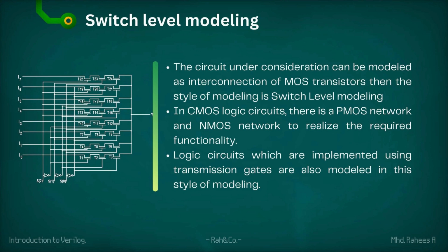Here in the diagram, an 8:1 multiplexer is represented as an interconnection of various NMOS transistors. The circuit under consideration can be modeled as interconnection of MOS transistors. Then the style of modeling is switch level modeling. In CMOS logic circuits, there is PMOS network and NMOS network to realize the required functionality. Logic circuits which are implemented using transmission gates are also modeled in this style of modeling.